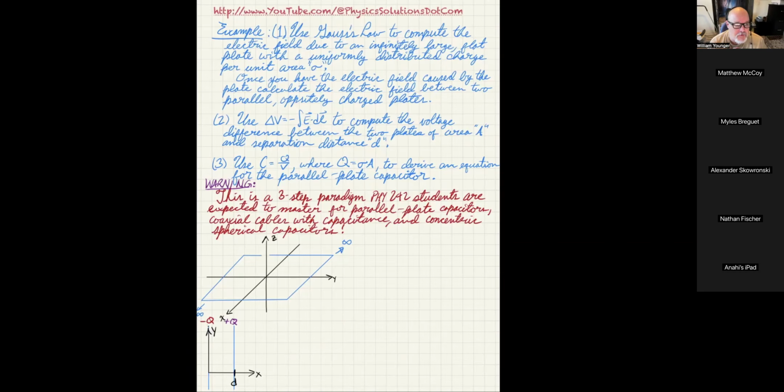For instance, the three cylindrical ones that I showed you in the opening photograph for the chapter: the top of them, since it's cylindrical, is shaped like this, but it has more or less the logo for a Mercedes, a line down that then breaks into a V. And when the capacitor fails, usually what happens is it blows up a little bit and pops that Mercedes symbol into three little slices, and those three little slices stick up. That's how you can tell that the capacitor has been ruined.